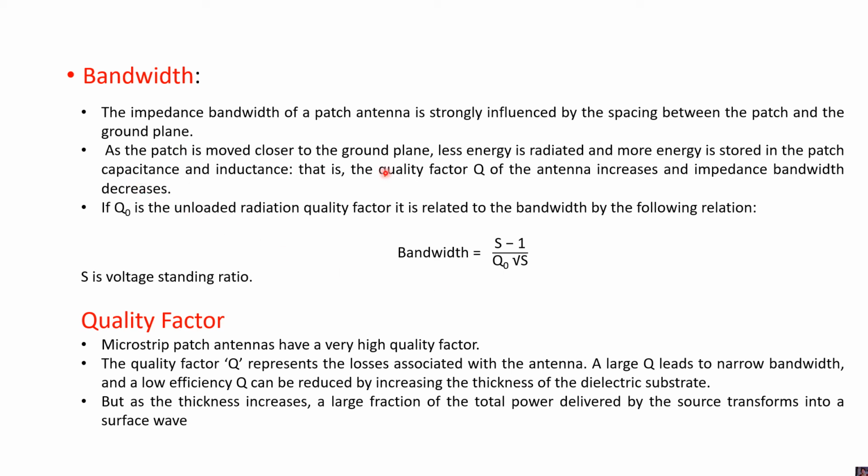So as the patch is moved closer to the ground plane, less energy will be radiated, and it is also a factor of quality factor. Bandwidth is given by (S minus 1) divided by Q naught into root of S. Q naught is the quality factor, and root of S is the voltage standing wave ratio.